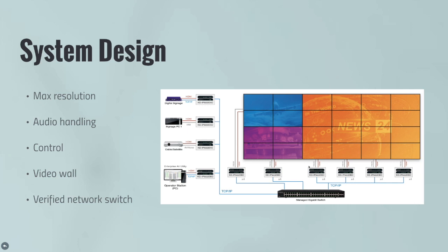Audio, do you need to break that out at the equipment rack? Then you should probably use some of our encoders with audio de-embedding. They also have lip sync adjustment on many products so that you can compensate for any latency that may occur. Because yes, anytime you're going through your network switch, you will encounter latency. And so that is another consideration of system design.